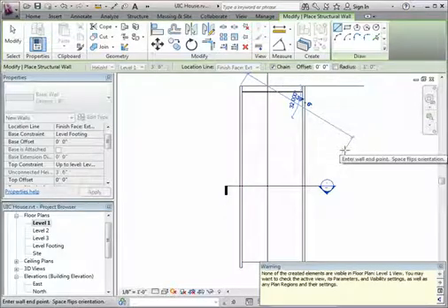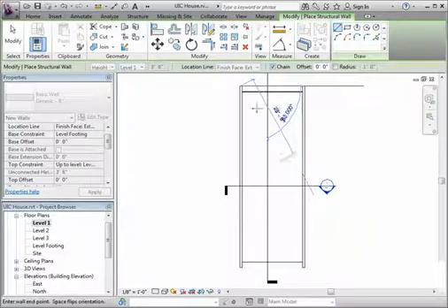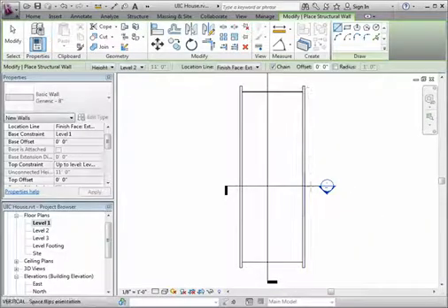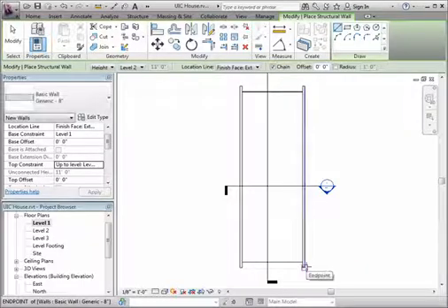And it's telling me that none of the elements are visible. The reason is because everything I just drew is below the first floor plan, right? And the first floor plan view itself actually has limits on how much you can see. You can set them at different limits. Currently you can't see below the first floor, so it's saying that it's not visible, which is fine for now. Pretty much know what we have. So I'm going to go in the other direction.